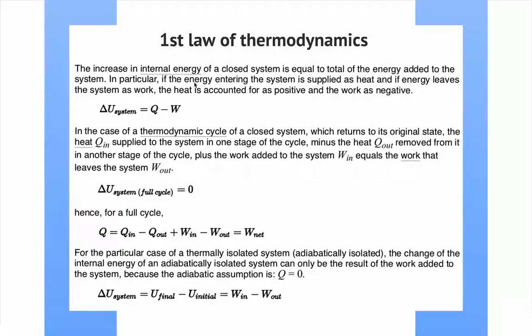Specifically, the energy entering the system is supplied as heat, and if energy leaves the system as work, which is generally the case in most heat engines, the heat is accounted for as positive, so this Q is considered a positive number, and the work is negative, which is why you have a negative sign here.